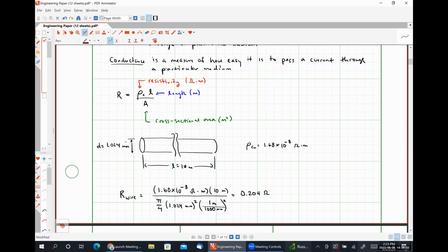So for those of you that go into a chemical plant or something like that, and you're working on setting up, let's say, HVAC systems for a new building, you want to make sure that your cable runs to your compressors and things like that are as short as they can be so that you don't have an appreciable voltage drop over those conductors, and so that the compressor of your HVAC system actually sees the nominal voltage that it's expecting.